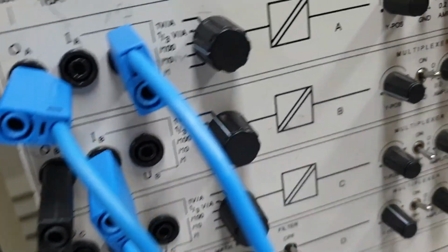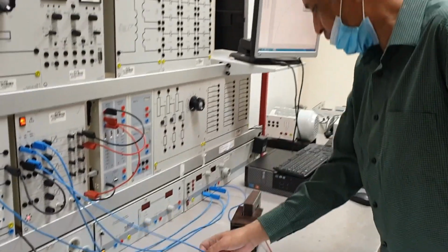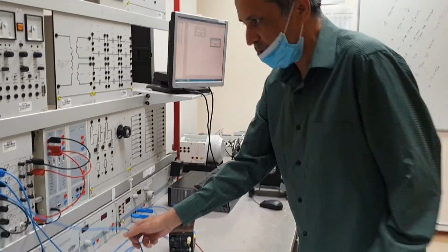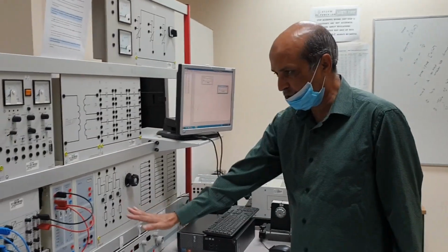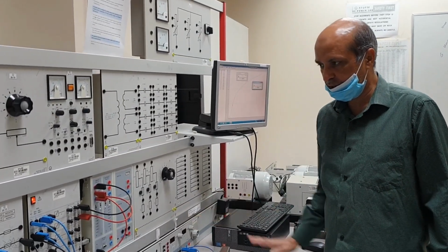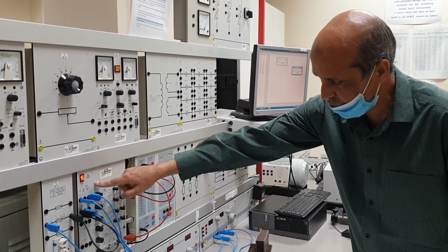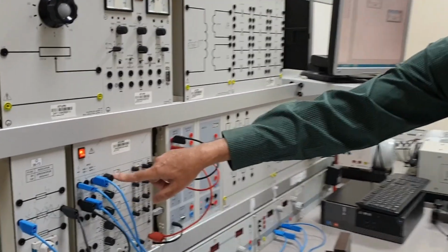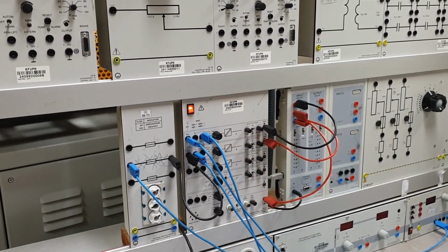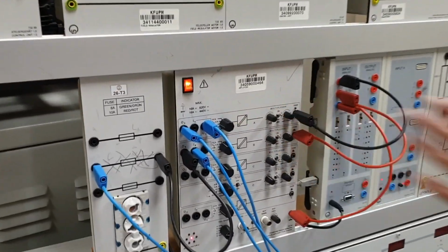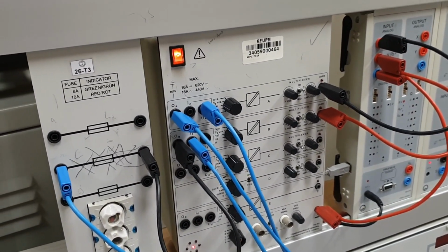Now the current, we are going to measure the current flowing through the core. So it is in series. So we need one fuse, as we are using a single phase supply here. So we are using two channels, one for the voltage. Channel A in the amplifier is for the voltage and channel B is for the current. So we have 1 V per A for the current and divided by 100 for the voltage, as you have seen in earlier experiments.